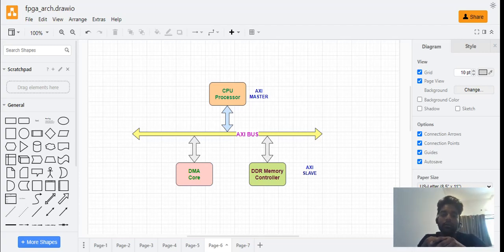So in that case, the common interface for any IPs, if you take the AXI bus interface, nowadays all the IPs are coming with the AXI interface defined on top of that. It's just like we need to create a wrapper on the conventional IPs, which can be used across in a common way. It's a kind of common interface which can be used by other designers as well. So that's a key point here.